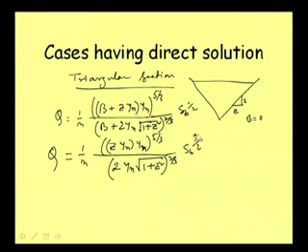Now in this expression it is interesting to see that the numerator will become y n to the power 10 by 3, and the denominator will become y n to the power 2 by 3, and these are in product terms. So you can just bring y n out of this equation and express it directly in terms of the other variables, that is Q, B and Z. So you can bring y n explicitly and solve for y n.